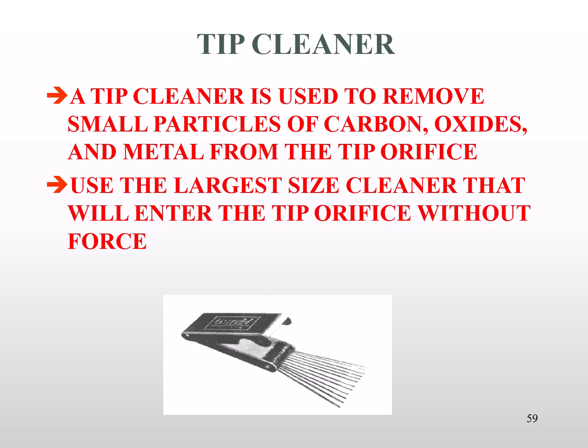For some reason, and it happens occasionally, you'll have a tip that'll pop because it's too close to the work. And sometimes that melted metal will come up at the edge of the tip. It'll cause the flame to distort and split. Well, the process is we would need to clean that tip. There are tip cleaners, as you see here, all over that lab.